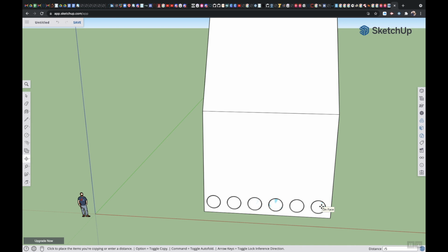Let me do that again. I'm using a Mac. Let me select this and get the move tool. I'm holding down the left click, still holding it. On my Mac, I hit Option while still holding my mouse. For Windows, you tap Control. Now I can release my mouse. Now I'm going to type /5, enter.